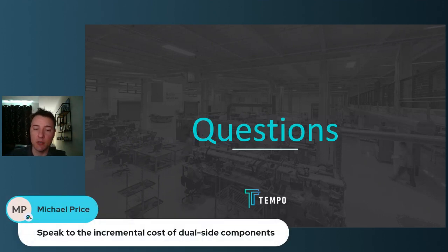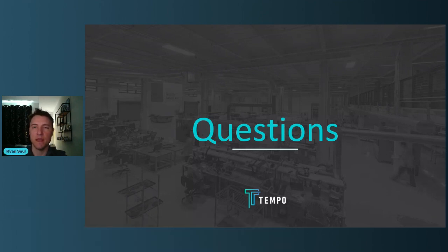So it used to be the case, I would say, that having a dual-sided assembly was a significant cost driver. It still drives cost, but it's not so bad. It's become relatively standard in assembly to have parts on both sides. As long as you're following best practices, like putting all of your most critical components on one side and a pile of passive components on the other side, you're really not going to be adding a significant amount of cost. It's when you have that stacking or compound complexity associated with maybe putting the wrong parts on the wrong side of the board.